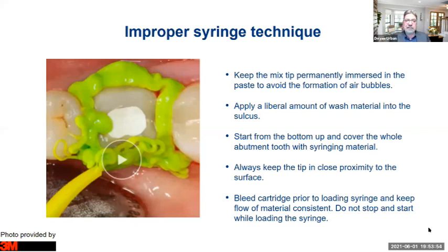And when utilizing the auto mix cartridges, bleed those cartridges prior to loading the syringe, because sometimes you'll get more of one side of the material than the other. You might have more of the base come out or more of the catalyst come out, and that's going to give you an insufficient mix. So do not stop and start while loading the syringe.